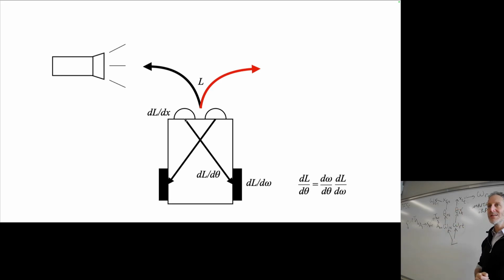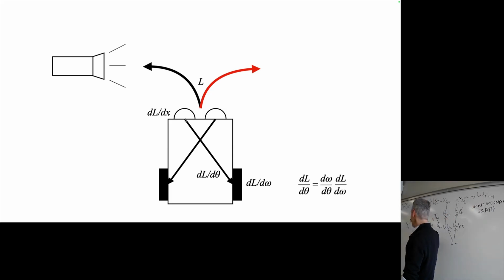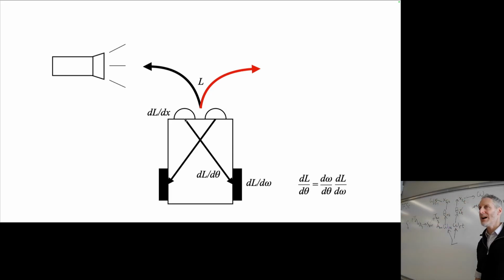So when I tell you that the differentiable simulator is able to calculate and then in some cases apply the local gradients, it's actually computing the local gradient, and it's able to tell us how to change this theta at this time to reduce L. It also tells us how to change the same theta at the previous time step. There's 1,000 instances of this variable in the computational graph. Everybody see that? So what do we do with theta sub L? How do we actually change theta sub L once we've got all the way back through the computational graph?